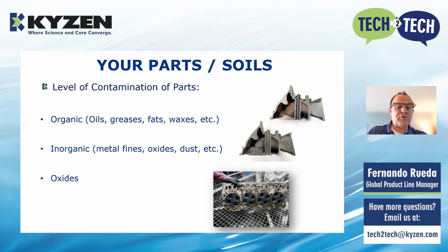We're moving now to your parts and the different soils or contaminants that you're removing. Parts can release different oxides or undesirable residues that could create reactions or sediments that could contaminate your bath faster, and then make you change that bath more frequently, which is typically undesirable depending on the conditions.